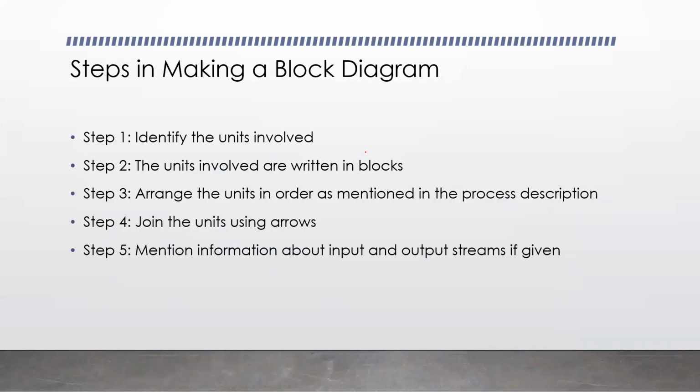All right. So now let's go on to steps in making a block diagram. So when we have to form a block diagram. Block diagram is very important. Why am I stressing on block diagrams right now? Because when we will be dealing with material balance problems, then the first step to solve a material balance problem is to form a block diagram. All right. So you need a block diagram for solving any material balance problem.